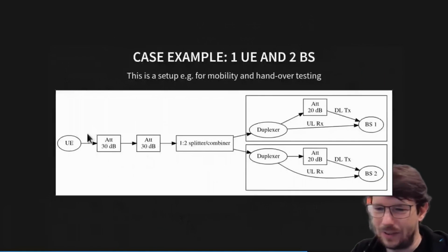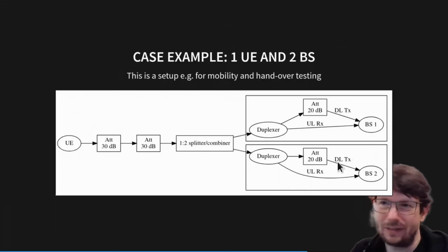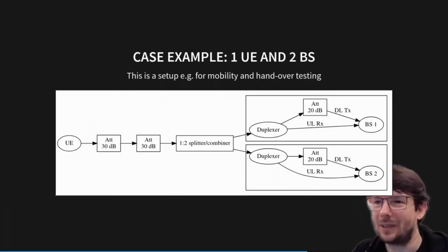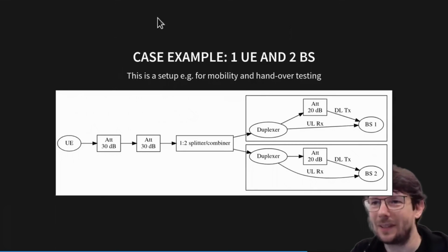So you could basically attach one port here and another port, I don't know, somewhere here, and with no UE and base stations and so on connected, you get your total attenuation over the entire network, over a configurable frequency band, and you basically can measure whether it does what it's supposed to do. But of course, network analyzers are rather expensive, so maybe not available for everyone. Just saying that's sort of the kind of things you can do.